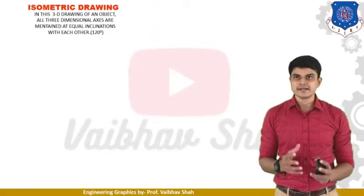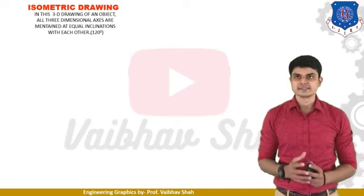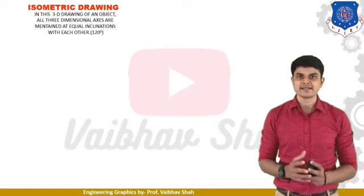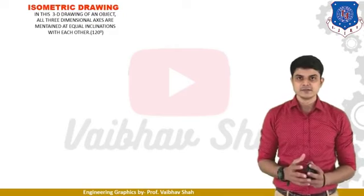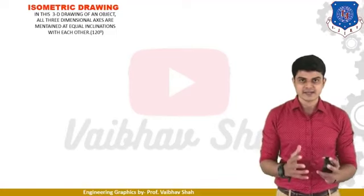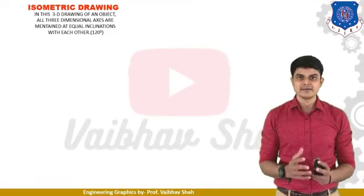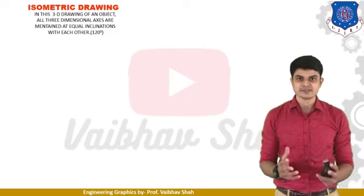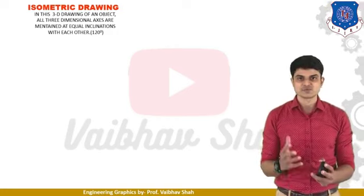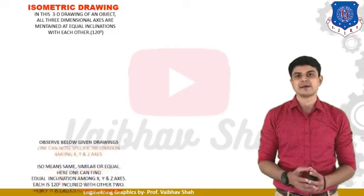In the 3D drawing of an object, all the three dimension axes are at 120 degrees to each other. As we know, the total circular angle is what? 360 degrees, right? So here iso means equal, and the angle is 120 degrees. So we make three axes of the dimensions 120 degrees apart, and we get one drawing which is nothing but your isometric drawing.